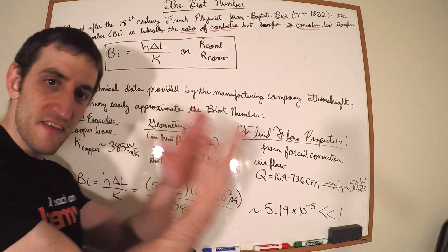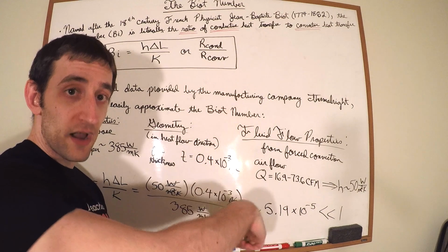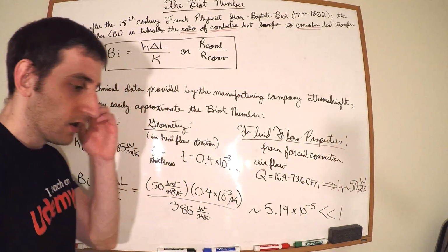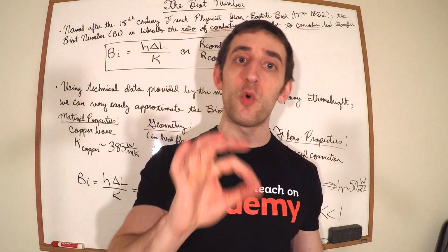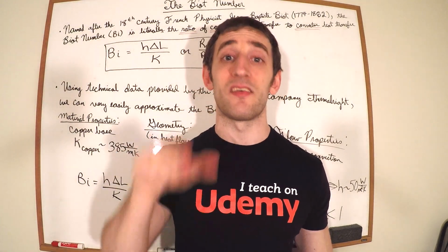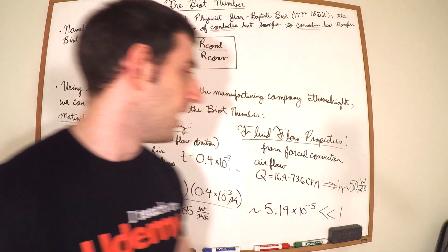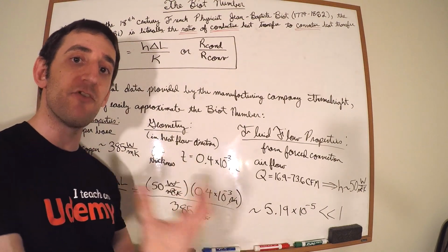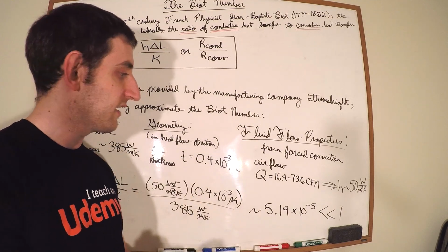We're going to get sort of an isothermal property in that fin, at least in the y direction. It's going to be different along the length of the fin. So that's going to allow us to say it's isothermal. We're going to be able to eliminate a coordinate that's going to simplify our lives. Less math for you. It's better. And then we can get to an answer for a problem, getting that temperature distribution and the heat transfer that's going through this heat sink very easily.